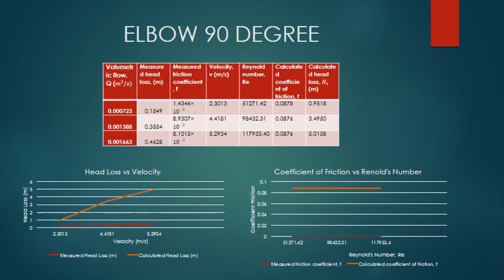However, the friction coefficient for calculated and measured value remain the same over time when the volume flow rate increases and Reynolds number increases. From data of measured and calculated values for head loss, the measured values are lower than calculated values, also the same, which is abnormal since some of the values are distorted by some errors.